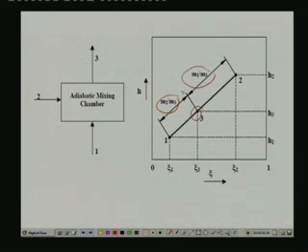For example, as m2 by m3 increases, this point will shift to this side. That means the exit condition will be moving closer to 2. Similarly, when m1 increases, this point will shift in this direction and the mixture condition will move toward 1. If m1 or m2 is 0, then you will find that this condition coincides with 1 or 2.